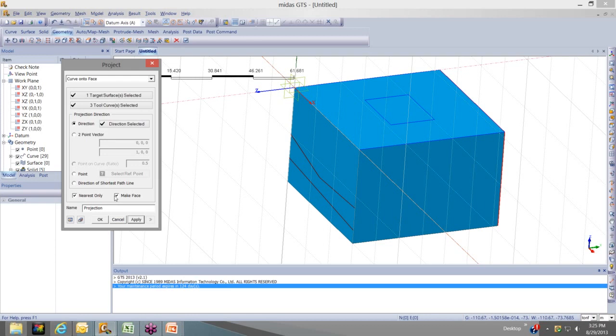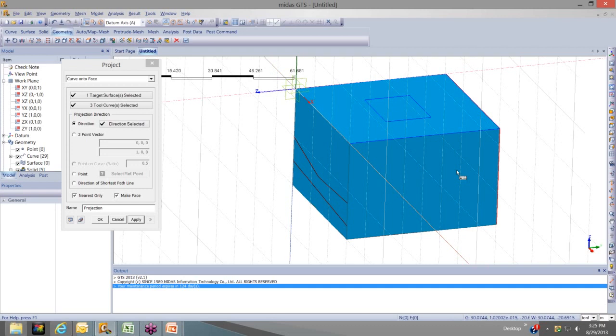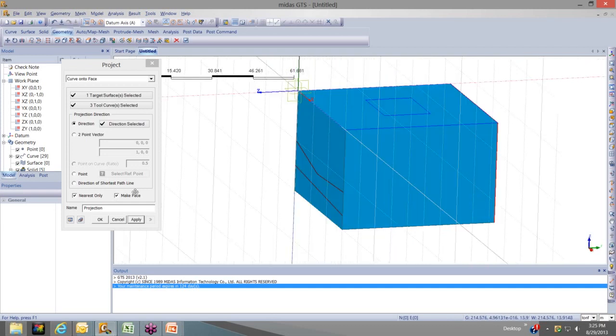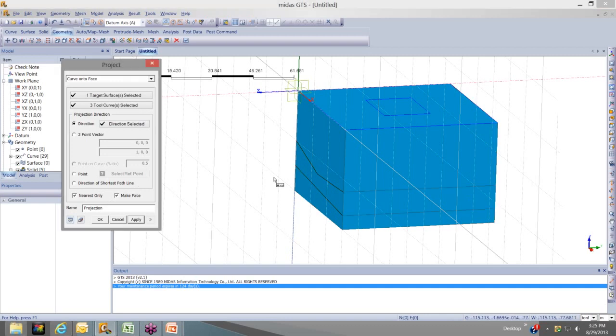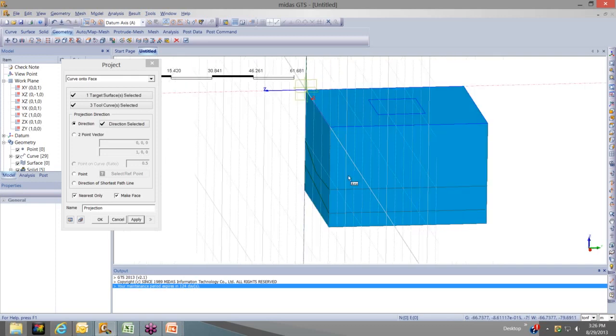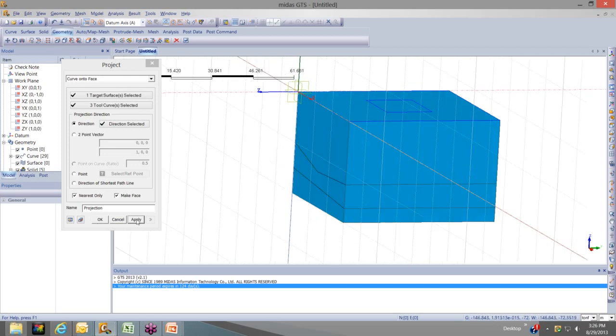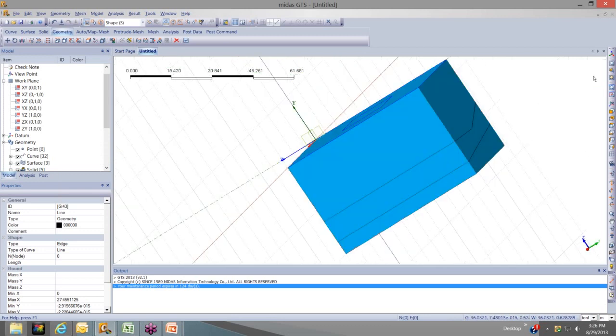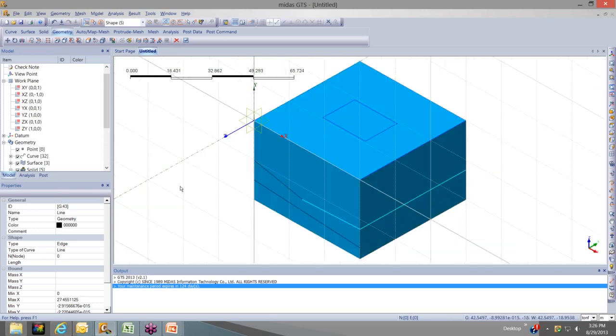This is particularly important because if you don't select this option, these shapes will just be imprinted onto this other side or this face, but there won't be an actual frame with a surface in between. I'll show you what it looks like, but first, let's take a check. As you can see, the curves are being projected while also having this line here that represents the frame. And within that line, there will be a face or a surface that we'll use to cut our soil layers. So that looks good. Click Apply. And now we have our first two soil strata layers.